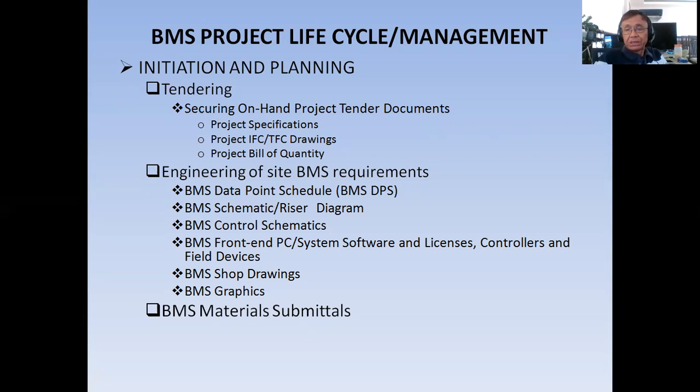So what is the composition of BMS material submittals? Now, in your BMS material submittals, you don't need to provide everything under the engineering of site BMS requirements. You can submit your BMS material submittals, which will show the BMS data point schedule, BMS schematic riser diagram, BMS control schematics, BMS front-end PC, system software and licenses, and controllers and field devices selection. So these four items, you can include in your BMS material submittals.